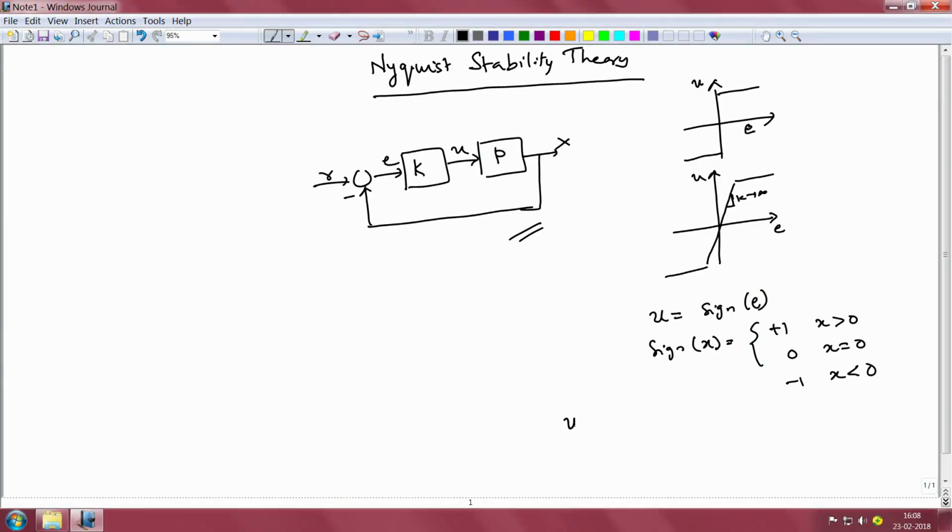One other simple extension to what we just discussed, namely on off control, is what is known as sliding mode control. In sliding mode control, we would have u to be the sign of not the error E, but rather some dynamic function of error, for example E dot plus E. Now what happens in this case is that when this kind of control law is applied, the system moves to the surface E dot plus E equal to 0. So this is a surface in the phase space of error and its derivative.